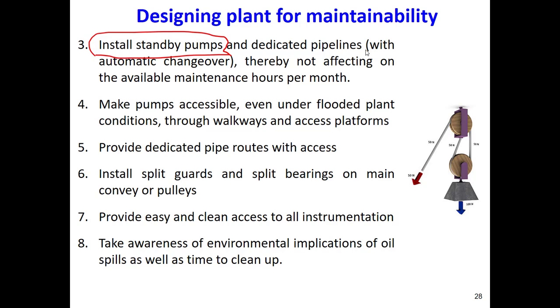And even for the pipeline, we have to dedicate some pipeline that is used for purging, for maintenance, for this kind of work. Then as I said, we should design lifting devices and moving devices to move and lift the equipment, and we have to locate them to be accessible.